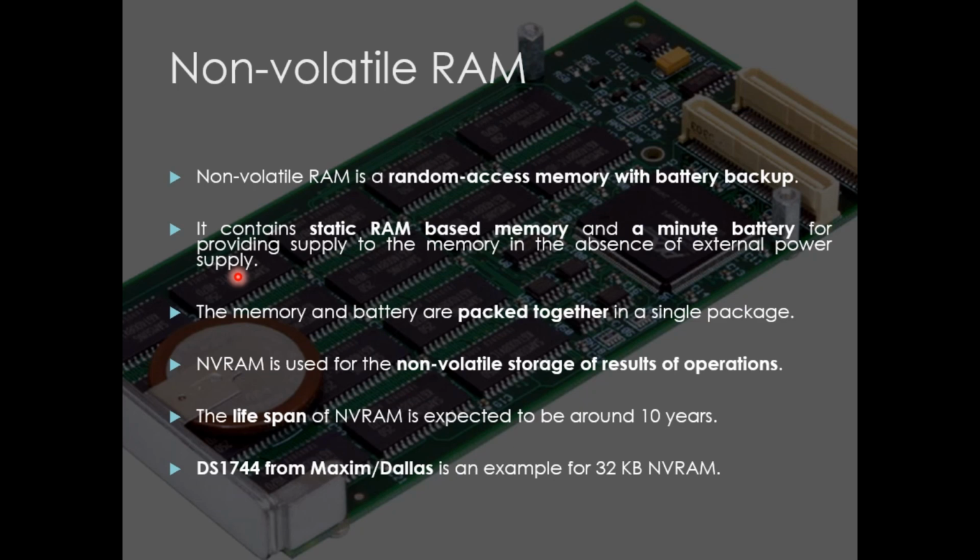Right, getting it? Now the lifespan of such memory is expected to be around 10 years. An example for a 32 kilobyte NVRAM which I can give you is the DS1744 from Maxim Semiconductors. So that is one example for a 32 kilobyte NVRAM.